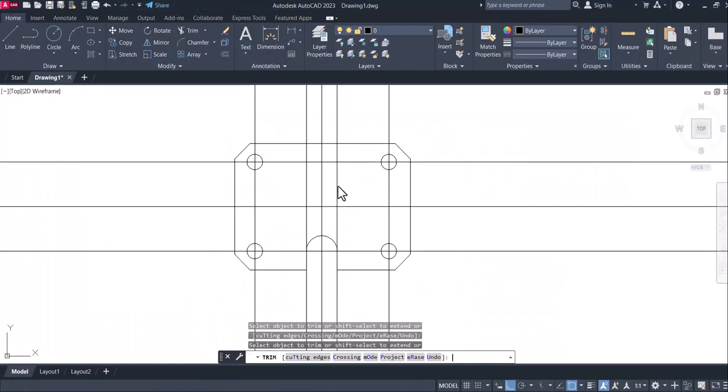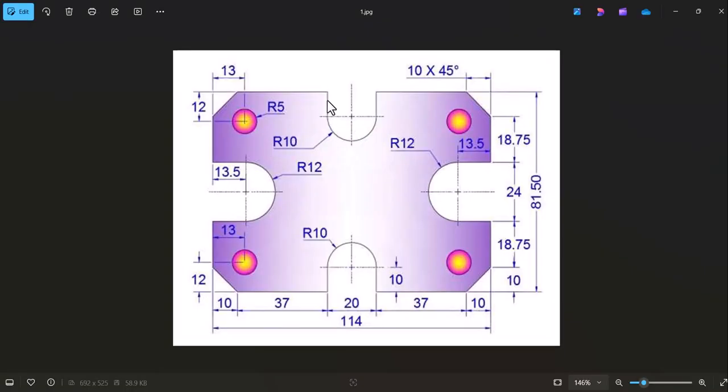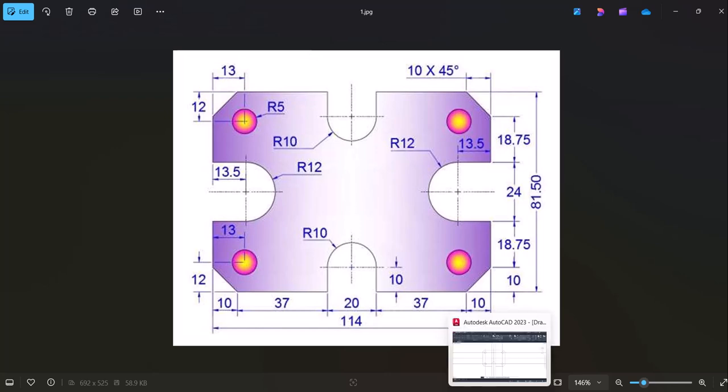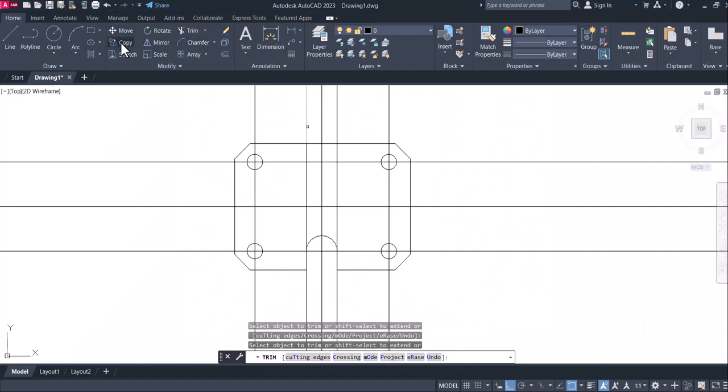In order not to have a too confusing drawing, let me check if the same distance is here, radius 10. I think the same measurement here is the same that goes up. How do I know? Now I have this radius as 10, which means from here to here is 10, from here to here is 10, which is 20, which is similar to this. So it's the same dimension. So I'll go and do it for the upper part too.